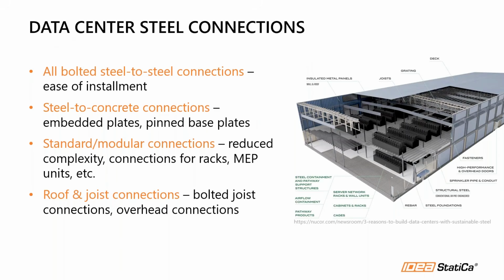So the most common, your bolted steel-to-steel connections. These are widely used due to their ease of fabrication and installation, and they make ideal candidates for their standardization and reusability across many different projects. Your steel-to-concrete connections, these include your embed plates that are attaching to the precast walls or pin base plates that are attaching to existing foundations.